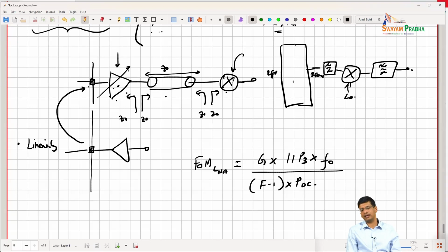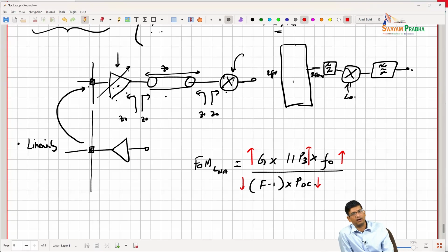So this, again, the usefulness of this is to see what is hard, right? So increasing frequency is hard, increasing linearity is hard, increasing gain is hard, right? Decreasing PDC is hard, decreasing noise factor is hard, right? So if you have a good figure of merit, these are the constraints that you're operating under, and usually it also means that there are trade-offs associated with all of these, that if I want to get high linearity and at the same time I want to get low noise figure, there is a trade-off space associated with it. It's tough for me to do that, right?